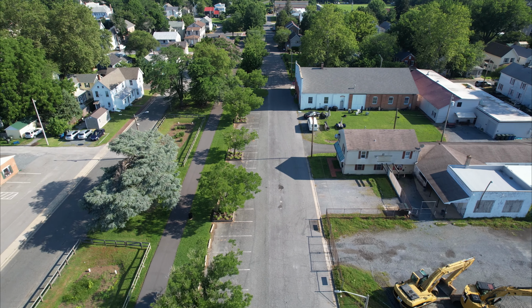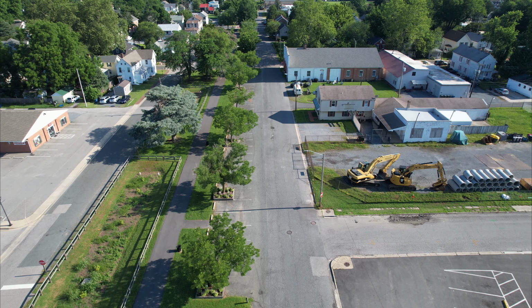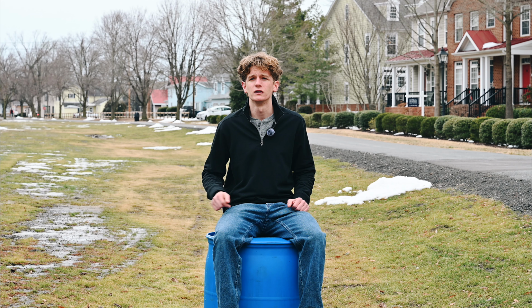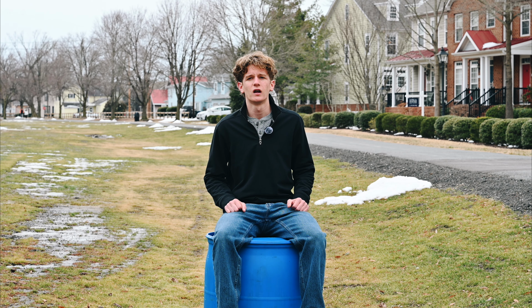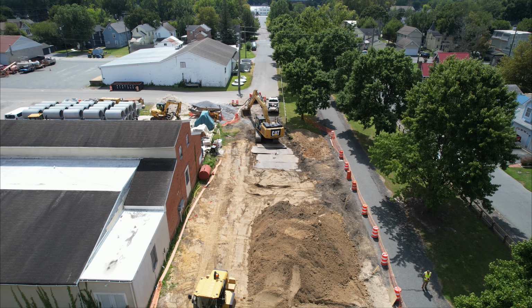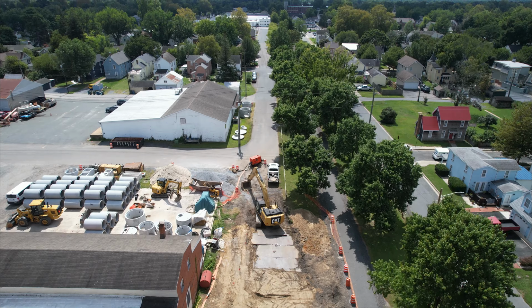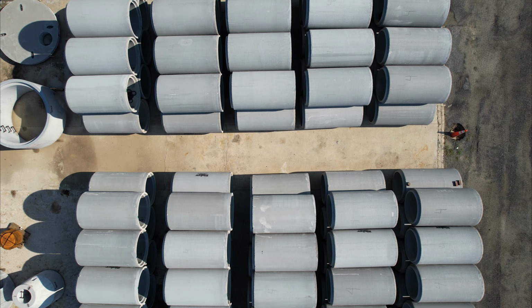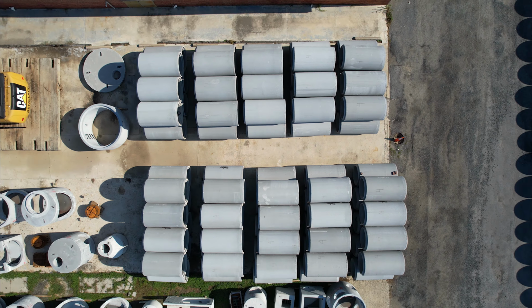It is expected that the flows of this storm event will be in excess of 100 cubic feet per second. For reference, 100 cubic feet per second is equivalent to 14 of these 55-gallon drums flowing past any one section of pipe in 1 second. Said another way, 100 cubic feet per second is equal to the volume of the water coming out of 330 1 3/4-inch fire hoses. As the project progressed towards Eastover Street and the end of the new system, the pipe size decreased progressively, with the smallest diameter of pipe being utilized for the new storm drain main being 36 inches.